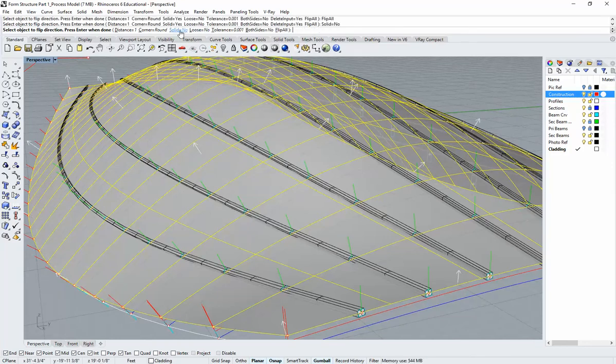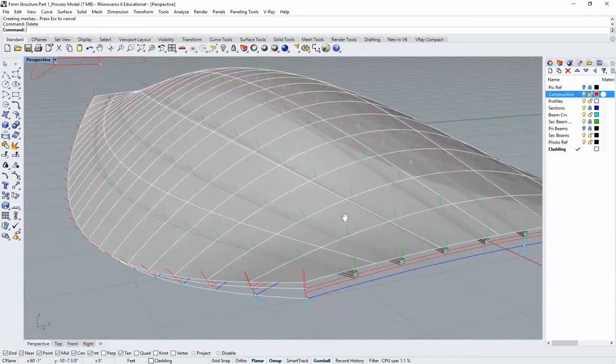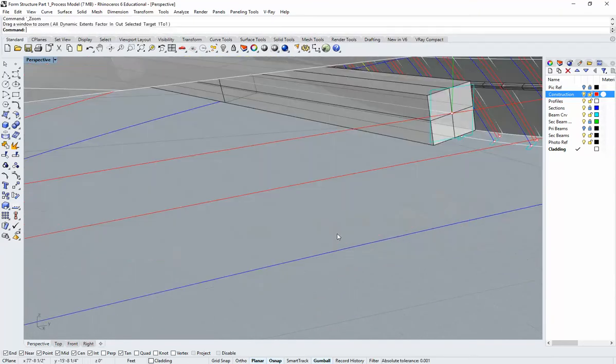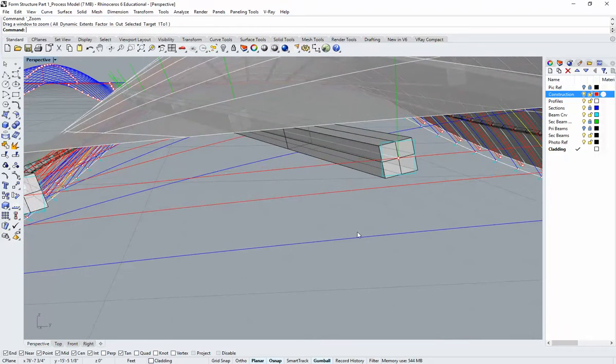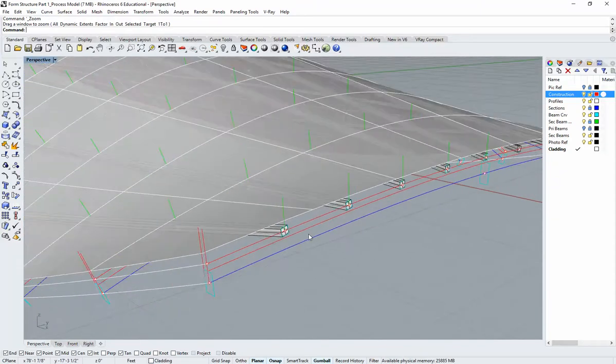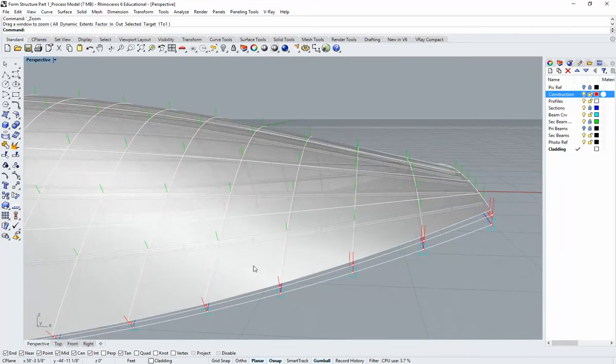I'm going to turn off solid, so that says solid no up at the top here. And then the distance we want to be, let's just say 7 inches. Should give us enough clearance. And then hit enter. And then you can hit enter one more time. And then delete the old one. So our new surface now, as you can see, floats over our steel structure so that there's no intersection at all. This is going to be the surface that we're going to use to base our curves against, the ones that go across the holes of the skin.